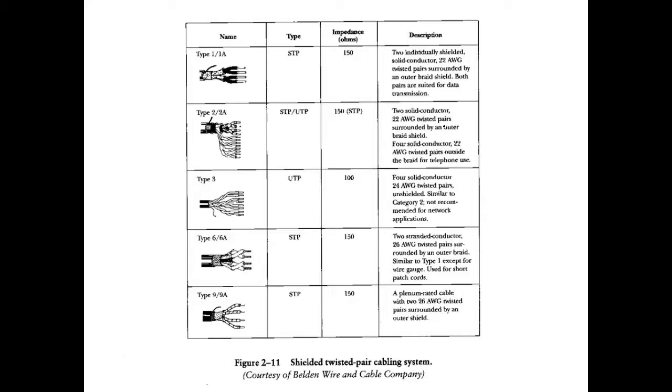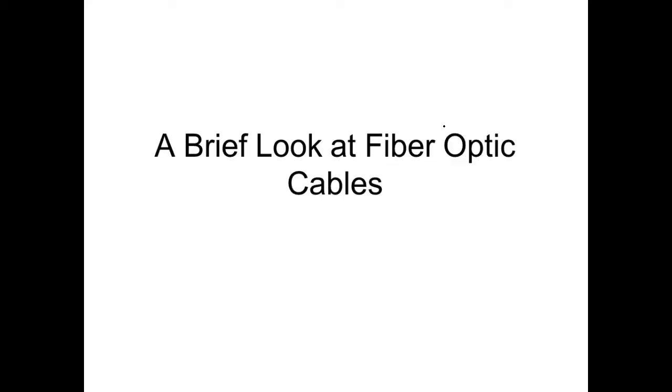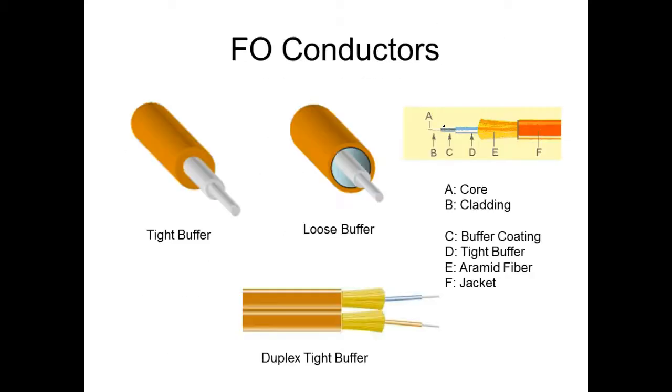Especially these RJ45s that we're using, you're going to have to untwist it some. The punch downs, you can pretty much carry those just about out to the punch down. But still, you got that space between where you terminate here and where it picks up on the other connector. This is just a basic look at fiber cable.